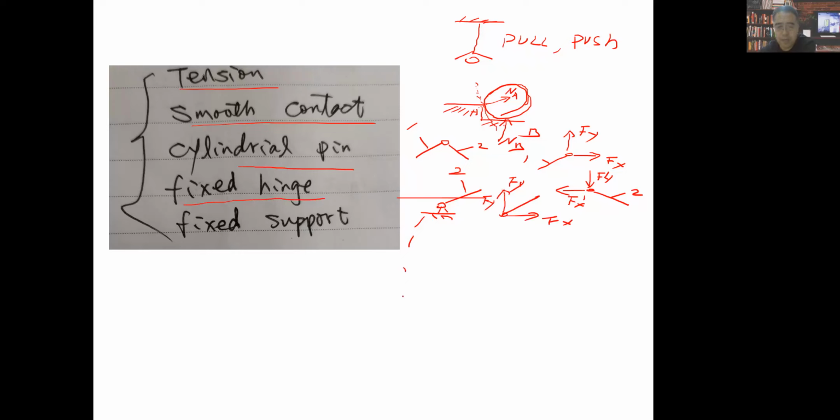Another one is this. So I will draw it like this. It is the fixed support in plane. In plane, we try to focus on this one, because in plane a free body only has three degrees of freedom, three capable movements. So we will give this, like point A, FAX to prevent translational movement from happening along the x-axis, and FAY and MA.